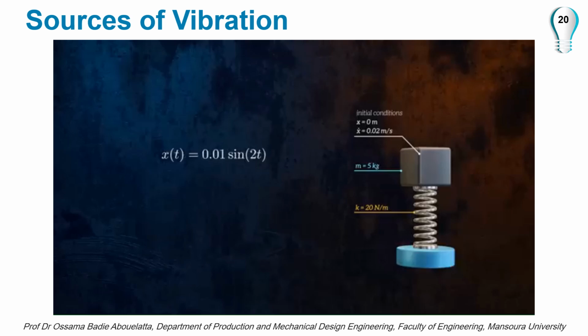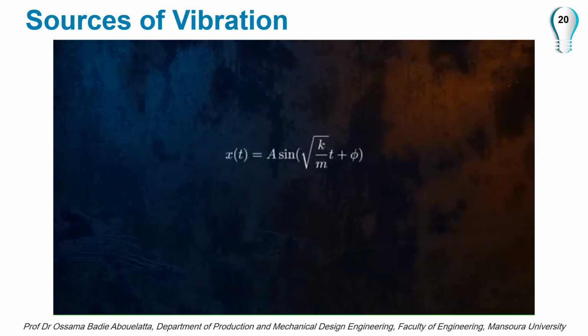An important property that can be calculated from a mass spring model is the system's natural frequency, the frequency at which it will oscillate naturally when in free vibration. It's given by this term in the equation of motion, and is denoted using the Greek letter omega. It depends only on the mass and the spring stiffness, so no matter what the initial conditions are, a system will always oscillate at the same frequency. It has units of radians per second, so is called the angular natural frequency.